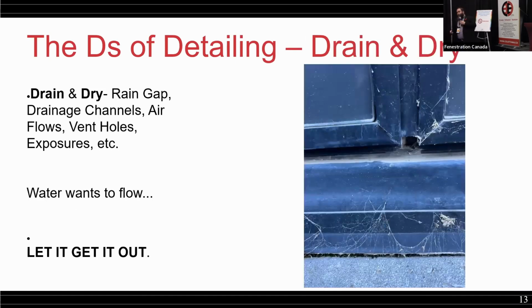Draining and drying. Oftentimes we come to site and we see, even in fairly new construction, of course, we should only be testing new windows and doors. What's new? Ultimately, we find a lot of the time these are filled up. Sometimes it's bugs. Every once in a while you get a spider nest. You get all sorts of different things that are blocking it. And of course, that can lead to problems because it's just not draining.